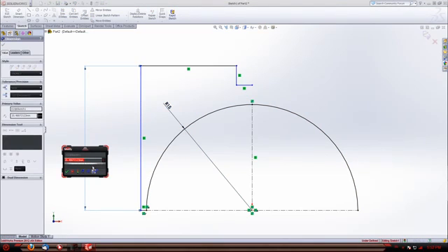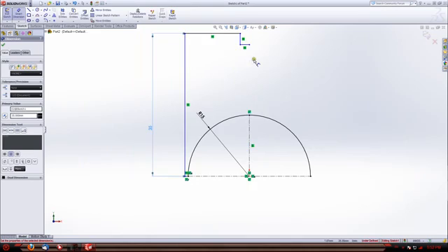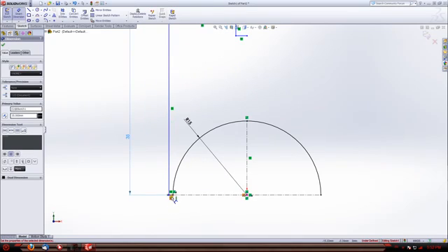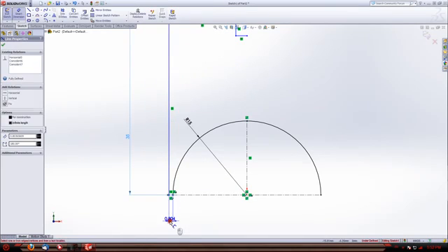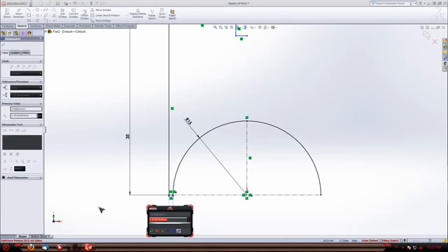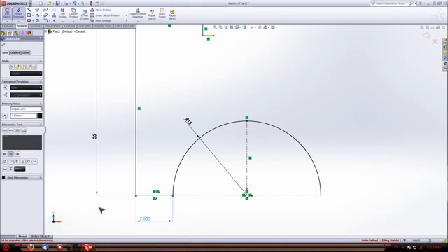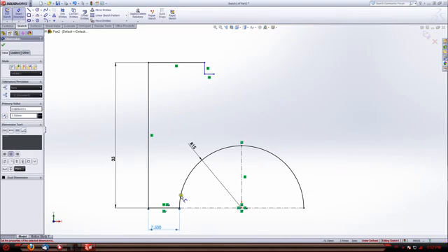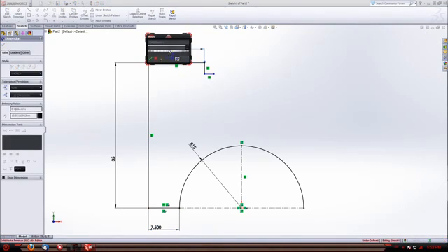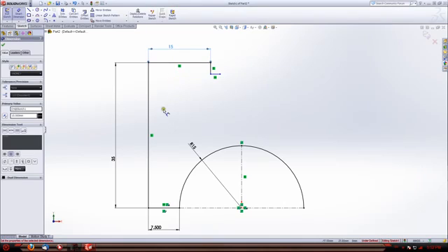This is 35. And the nice thing about SolidWorks is you can just sketch the general shape of whatever you're making first and go back in and add the dimensions later. And if you'll notice, my lines are turning black as I add dimensions to them. What that's doing is the dimensions are actually constraining where those lines sit. So after they turn black, they're unable to be moved. I can't drag them and move them around anymore. And that's what we want. That's a good thing.